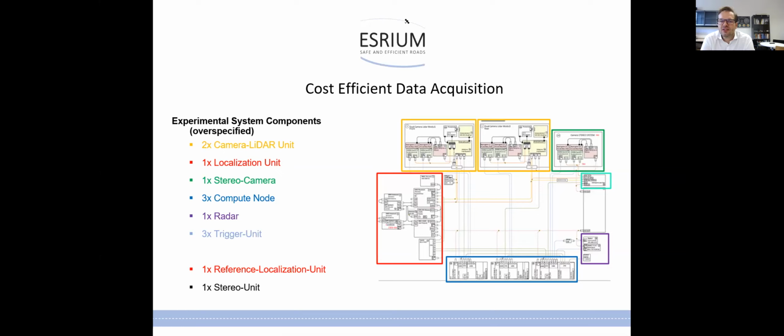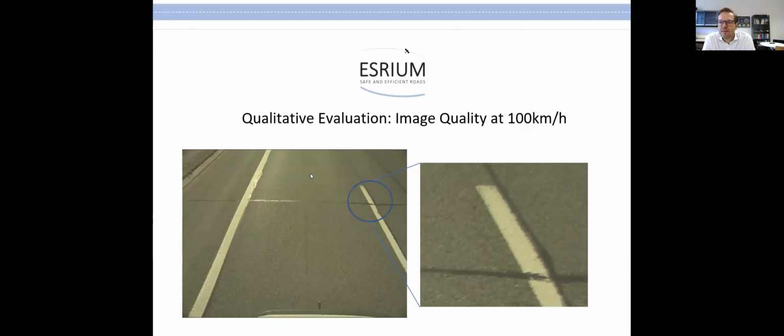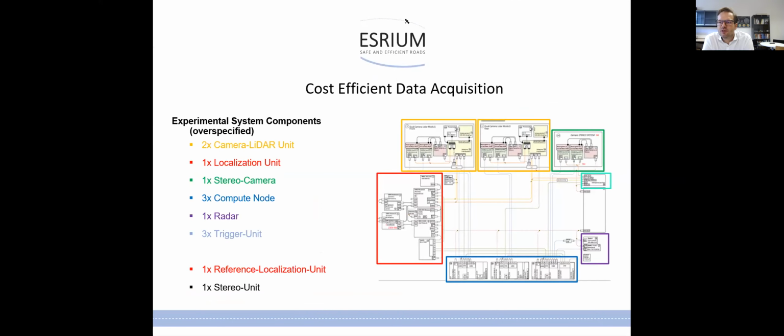They are triggered in a synchronized fashion, so that the scanning type scanners like the LiDAR trigger the cameras. As soon as the LiDAR beam enters a certain camera field of view, this specific camera is also triggered. Therefore, there is little temporal offset between 3D points captured by the laser scanner and 2D pixels captured by the camera.